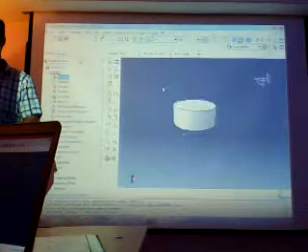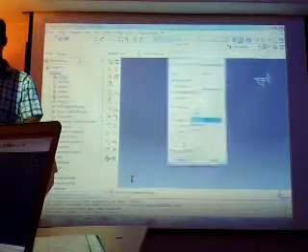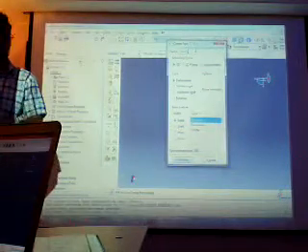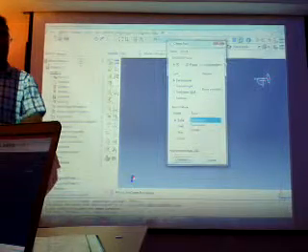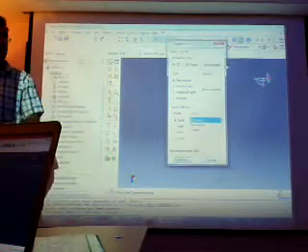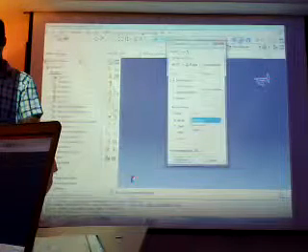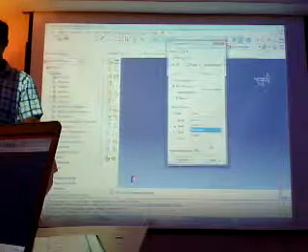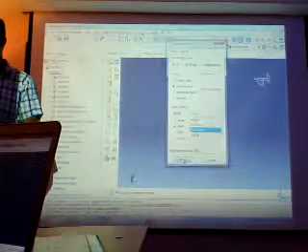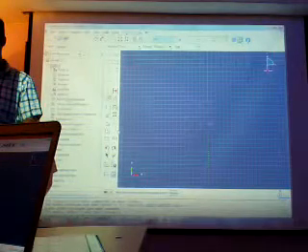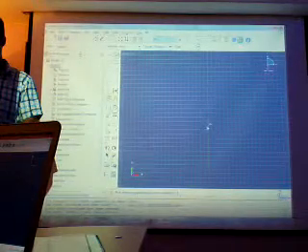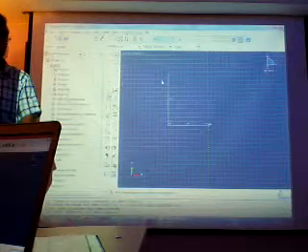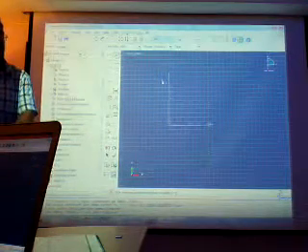Okay, so we need another part, the third part, the punch. But here we can put just surface pressure on the back. I will define the punch as a surface pressure. Okay, it's the punch: discrete rigid, shell, revolution. Also here is okay for this one. So for the deformable body, do you need to assign a reference point? Only for the rigid, yes.